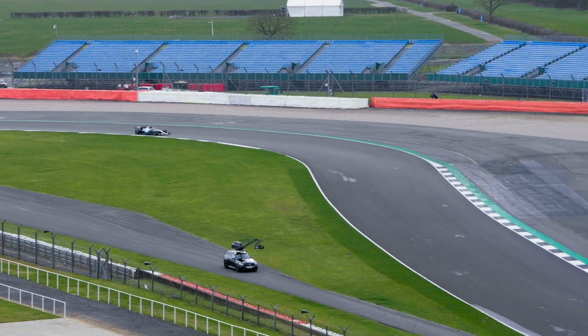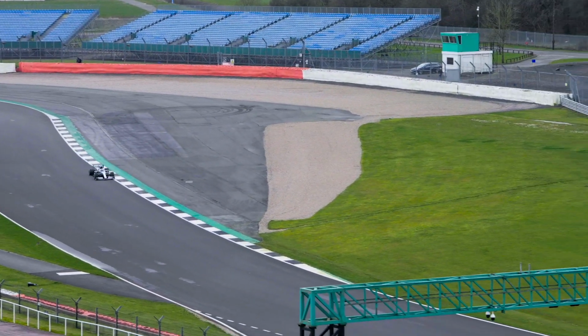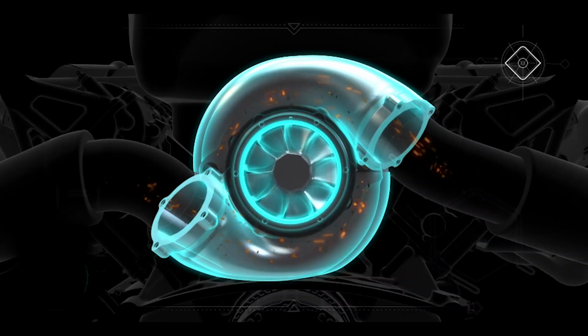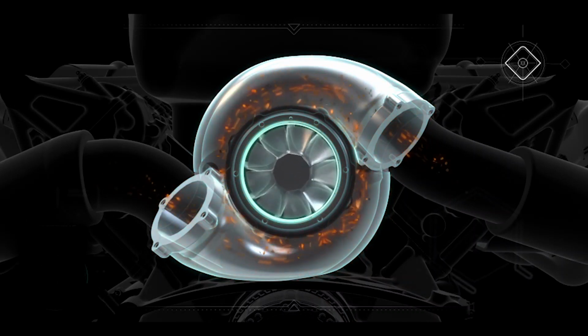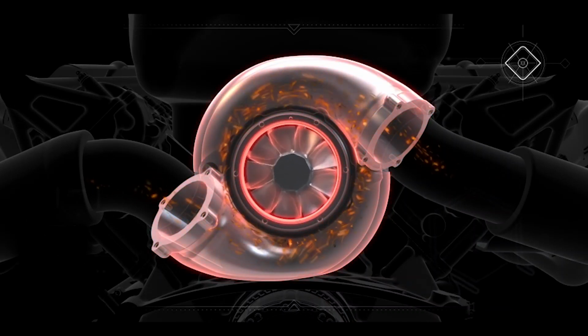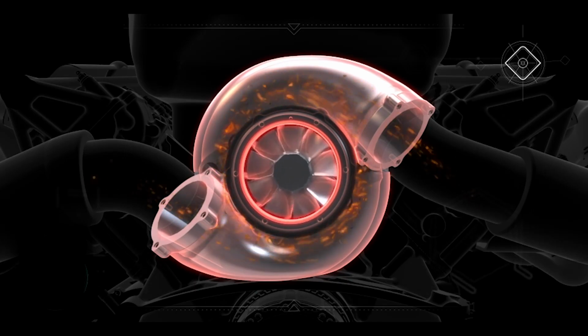This is the trend of road cars, and it's what's happened in Formula One as well, where you turbocharge an engine rather than making it naturally aspirated, and that allows you to downsize. So if you imagine when we were talking about the four-stroke cycle, and we were talking about when the piston on the induction stroke created a delta P in the cylinder, which then meant that the air could come in.